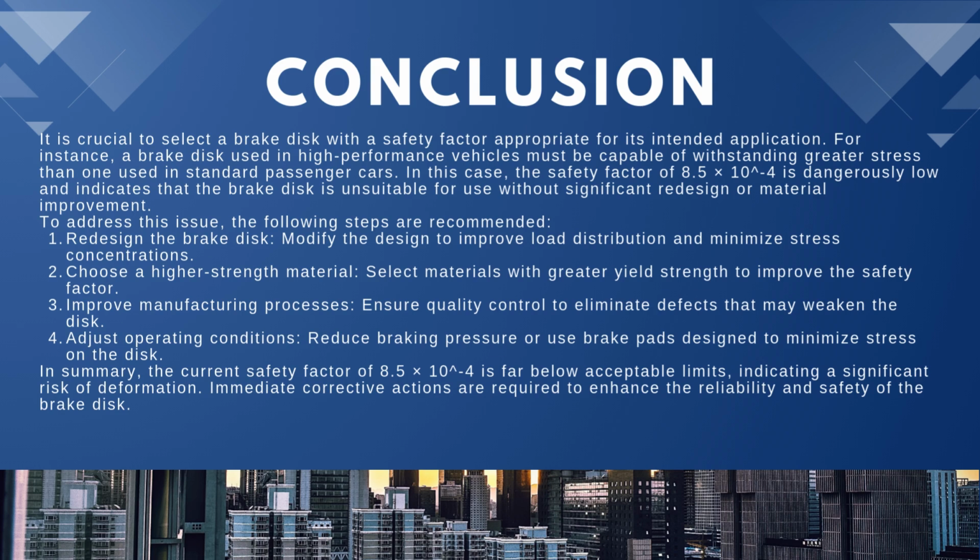To address this issue, the following steps are recommended. Redesign the brake disc, modifying the design to improve load distribution and minimize stress concentration. Choose a higher strength material, selecting material with greater yield strength to improve the safety factor. Improve manufacturing process, ensuring quality control to eliminate defects that may weaken the disc. Adjust operating condition, reduce braking pressure or use brake pads designed to minimize stress on the disc.